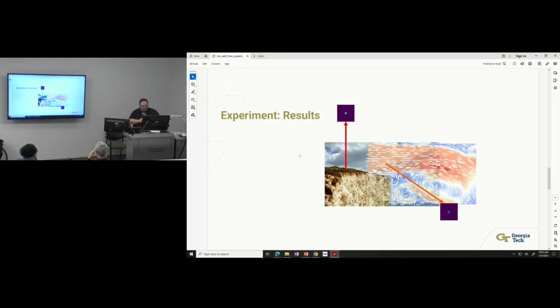I then attempted to relate, via Gladstone-Dale, the density. So the LES simulation solved for density, pressure, and velocity fields. You're doing compressible? Compressible, yes. So I took the data from the density fields and applied that through Gladstone-Dale to try to figure out the attenuation that a laser beam would face along different propagation paths and at a frozen instance in time.